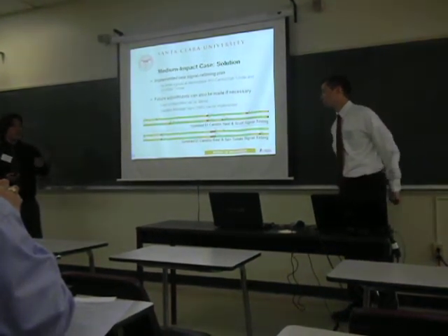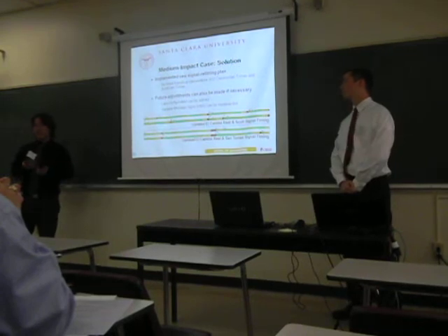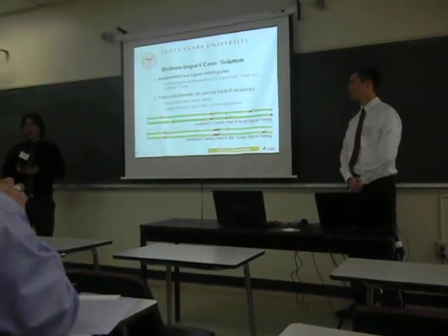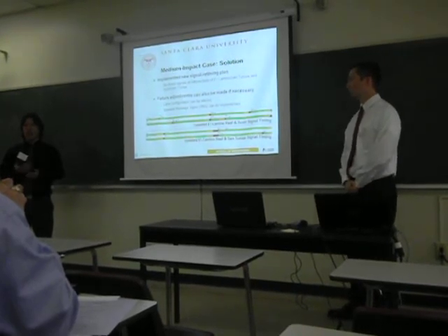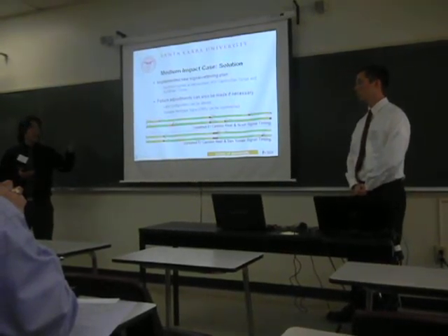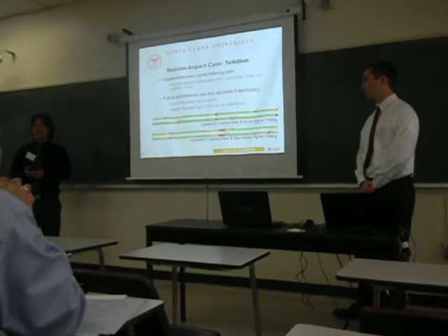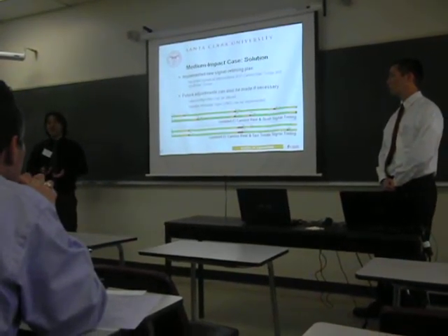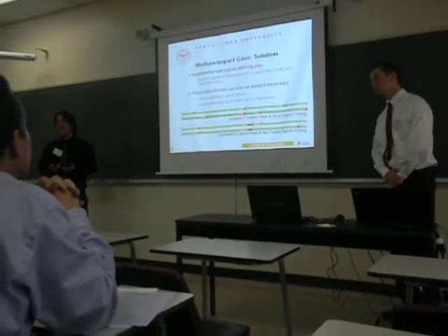Just a further thing to note: if there was still congestion and retiming these two intersections was not enough, we would propose retiming other intersections around the area, also possibly making lane configuration changes, such as adding more left turn or right turn lanes, and the possibility of adding variable message signs to warn drivers of what's coming ahead.